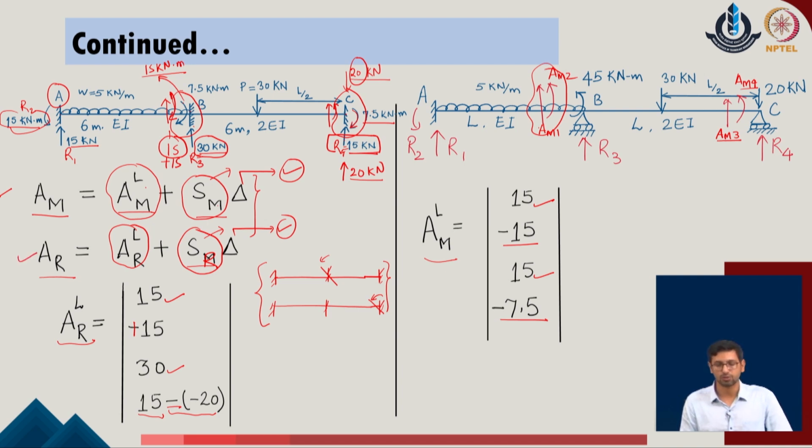So, once we have these values associated with the given problem, we can easily evaluate the net post processing of the given system. So, the general idea of evaluating the support displacements with respect to the free degrees of freedom which we did, along with that we are also now able to evaluate the external support reactions and the internal member forces of the given system. So, this typically concludes the basic discussions on the post processing of the given system.